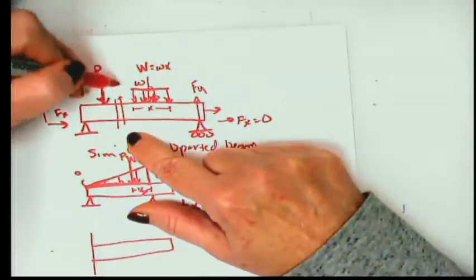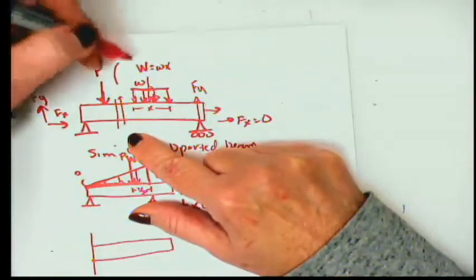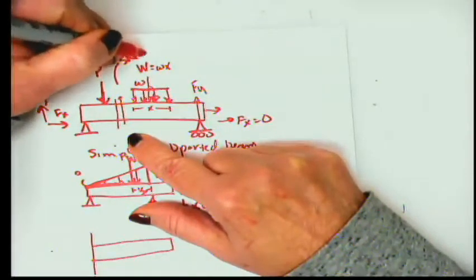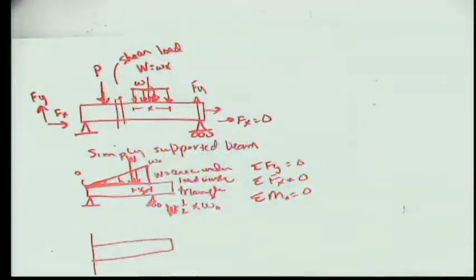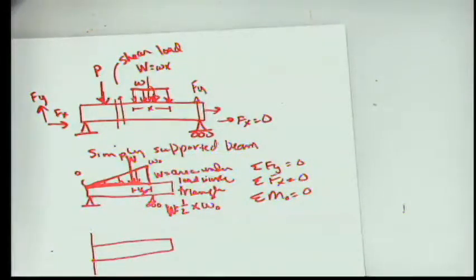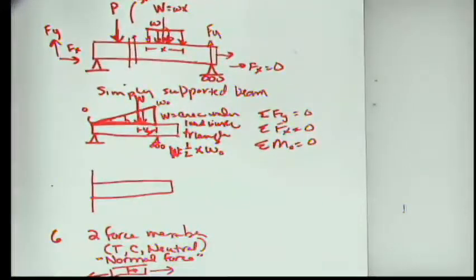And we refer to that not as a normal load, but as a shear load or shearing load. Right? So shear tends to create a shear plane where an object will try to pull against itself in this direction, whereas a normal force tends to pull it apart or push it together.